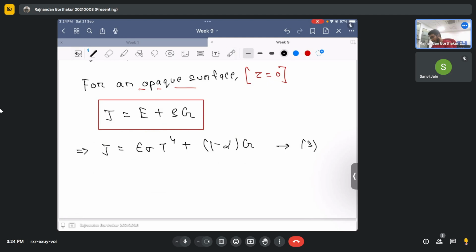Okay, and the next is we will determine the last flux. I mean, as I said, you can call any form of energy that leaves the surface per unit area a flux. In that way, you can determine your own flux maybe. But in principle, in radiation, there are essentially 4 fluxes which we need to consider when we are dealing with problems in radiation heat transfer. Of course, the first, second, and third being your irradiation, your emissive power, and the radiosity, and the fourth flux that we will see now is something which is known as the net radiative flux.